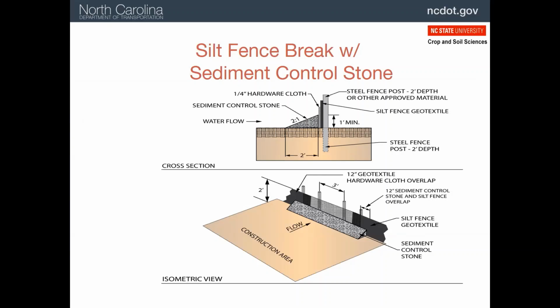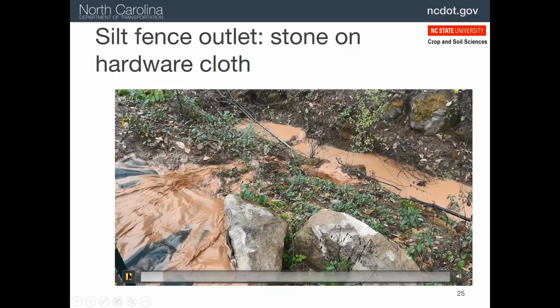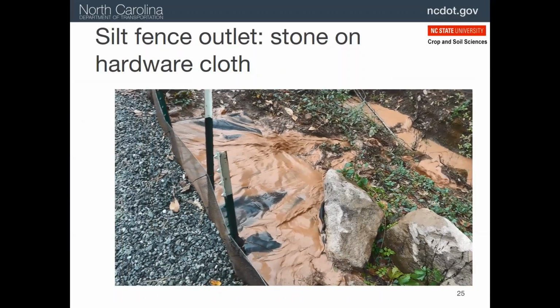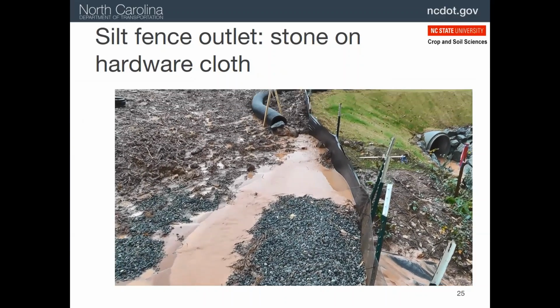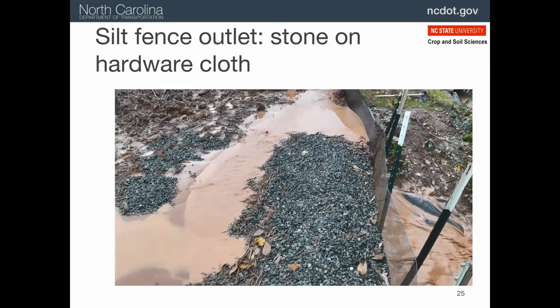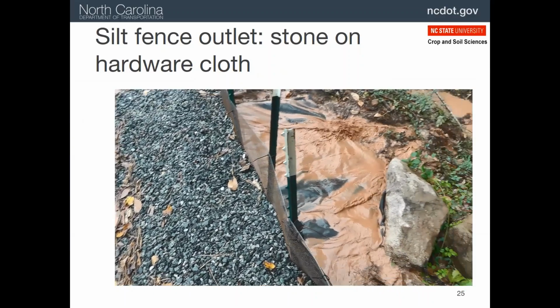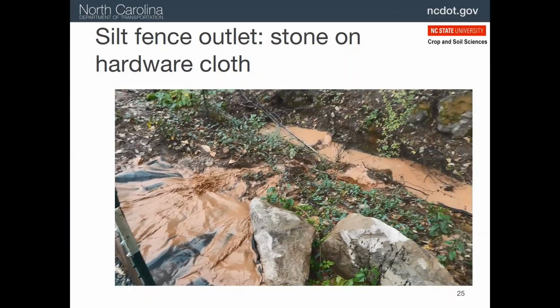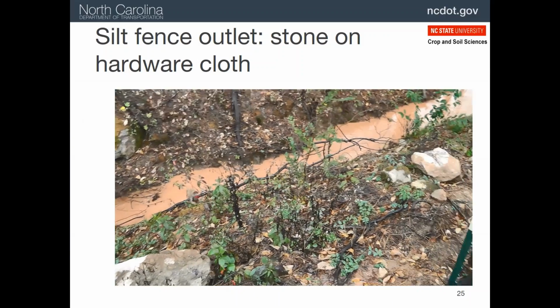The following video shows how this works during a runoff event. Here you can see the flow from a slope drain, which we'll talk about later, was directed down into this silt fence outlet. Some sediment is evident at the bottom of the gravel, as you can see. With most sediment control practices, the color of the water does not change because the fine particles are not retained behind these devices. We'll talk about how to attack those fine particles later.